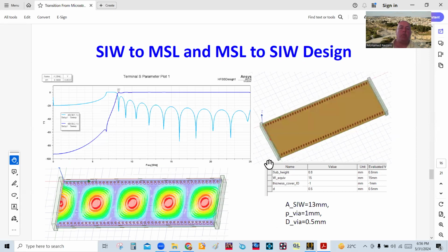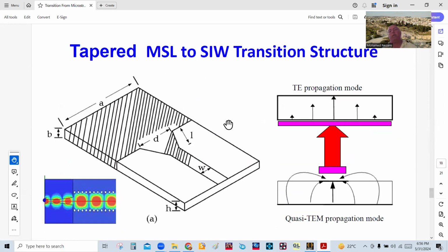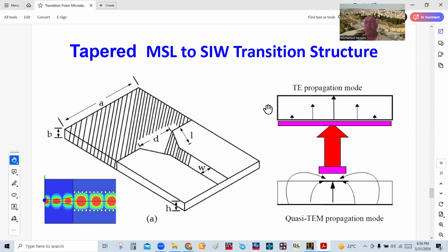So therefore, now we can go ahead and start thinking about how we are going to design a transition to this, okay? Because as you know, with the substrate integrated waveguide, you still have to attach a connector to it or get to a point where you connect to, say, the pin of a specific MMIC chip, or a passive component. So you still have to come up to a transition to a 50 ohm line like this, or whatever impedance it happens to be.